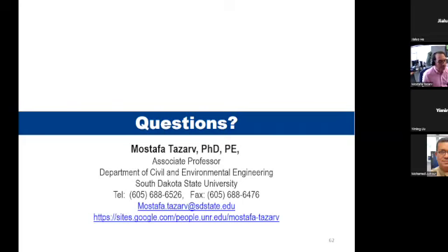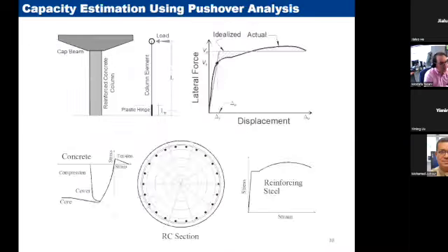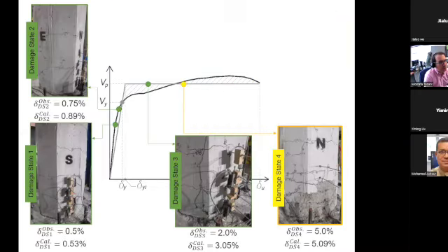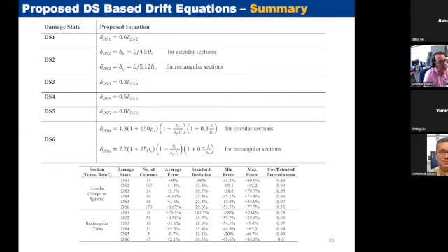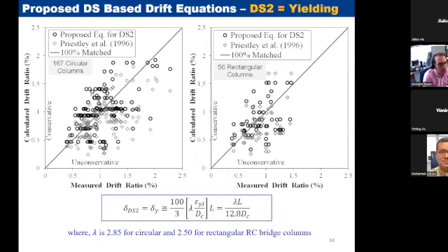Okay. The other question that I have is about the drift ratio and the calculation. We know that most of the experimental data that we collect is coming from columns tested based on fixed base in the labs. But in reality, you are going to have your columns as shaft columns, piles, or shallow foundation. I mean, that which is not common. Of course, the shallow foundation is state of California or Washington for rocking. So this is going to affect your drift ratio, the one that you calculated. So how do you guys handle this?